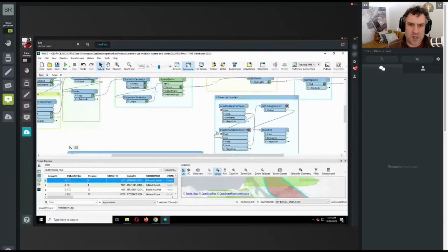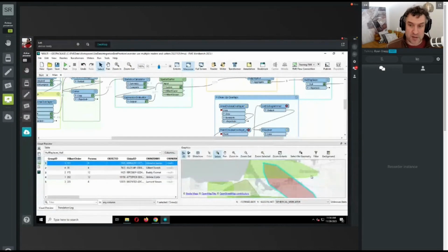So what this is going to do is, first of all, do an area on area overlay. That will create additional polygons here. So these two here will become 3 polygons. There'll be this polygon, the polygon where they overlap, and this polygon. Then we need to decide this polygon here, which polygon should that belong to?